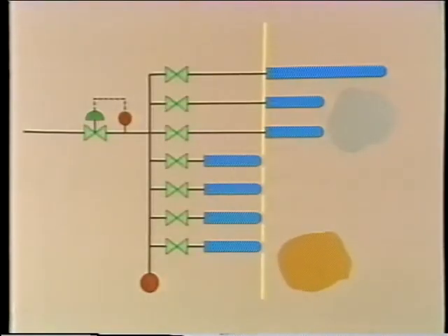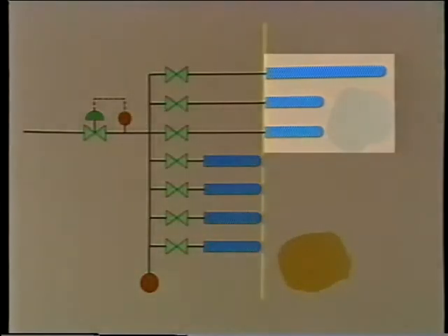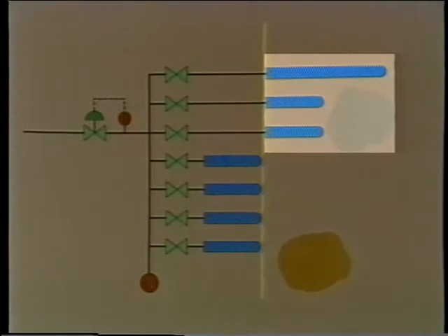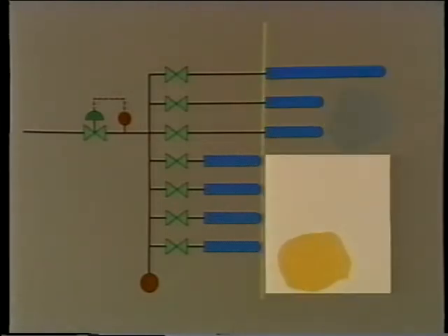Both fixed and rotating soot blowers are typically used in cooler passages in a boiler, where the heat and the passage of combustion gases won't harm the blowing elements. In hotter areas in the boiler, such as in the furnace where combustion takes place, the temperatures are too high for metals to withstand the heat for very long. In these areas, it's necessary to use retractable soot blowers.